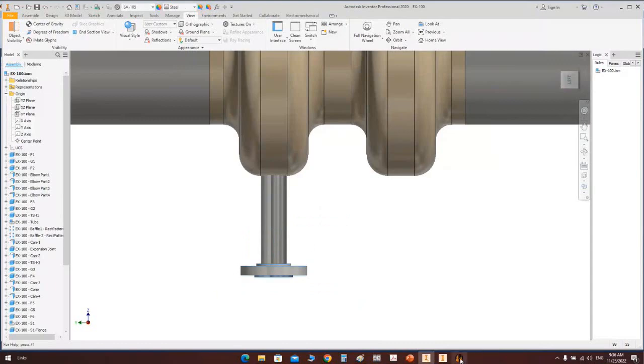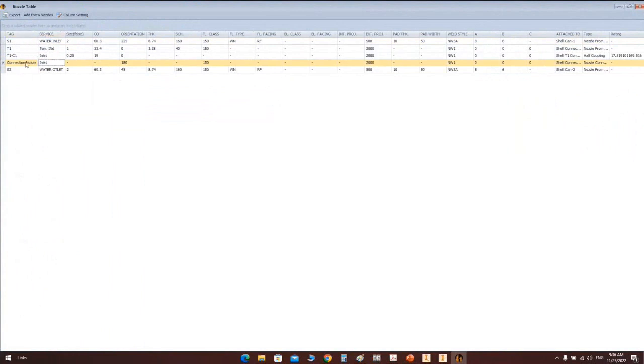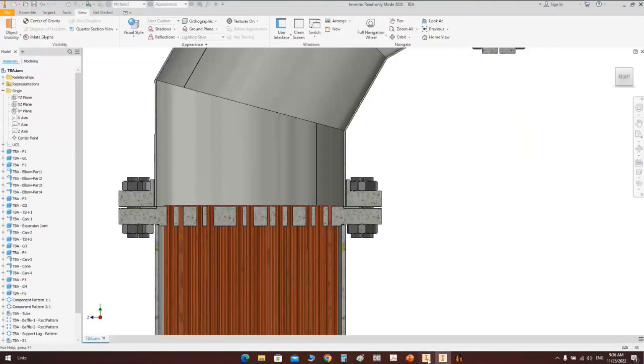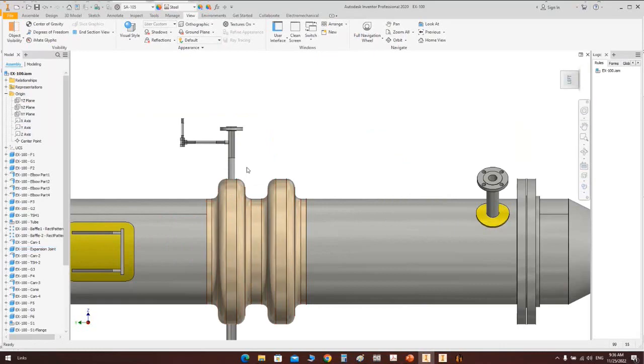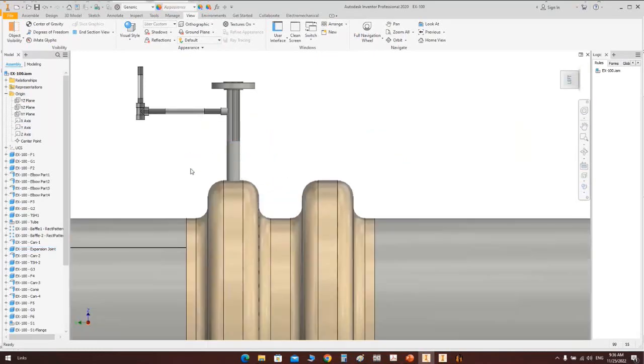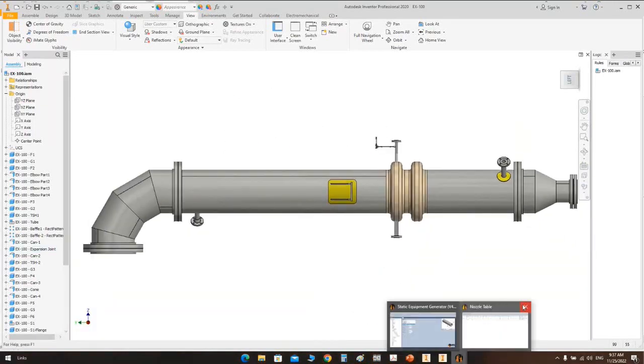So you will need to make a modification on that table after importing to your drawing regarding this nozzle. Okay, because it does not include the information of the attached parent element, because as we discussed, that's a parent element, not a nozzle yet. But that one is a nozzle because we're using a nozzle, so the information for this one is already included, and you can modify it on the table from SEG.